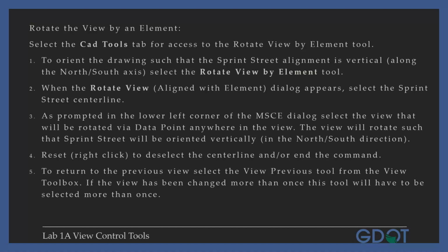To return to the previous view, select the View Previous tool from the View toolbox. If the view has been changed more than once, this tool will have to be selected more than once.